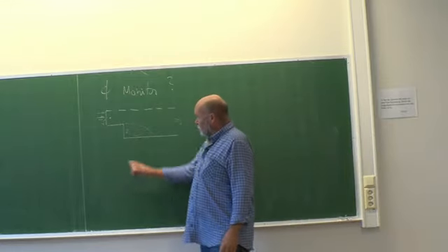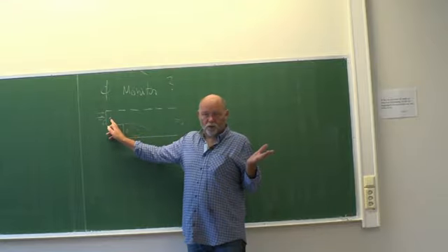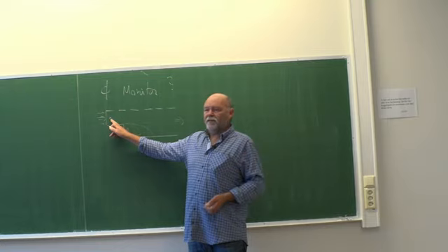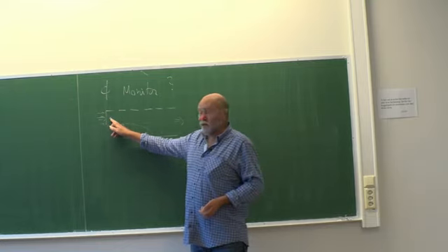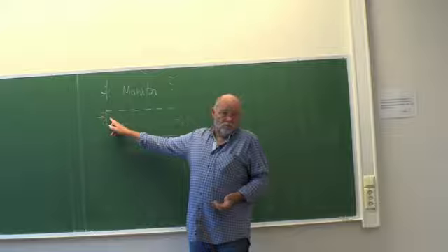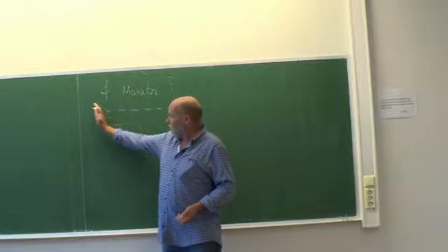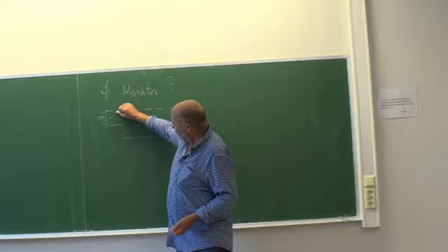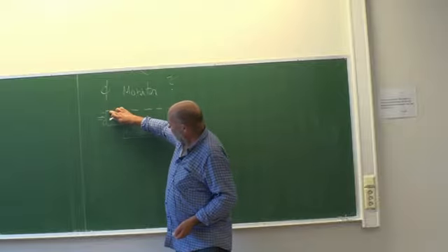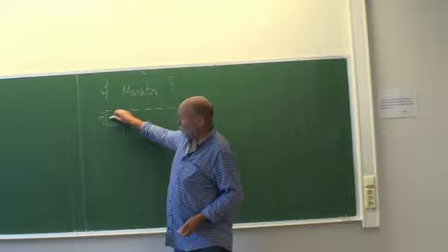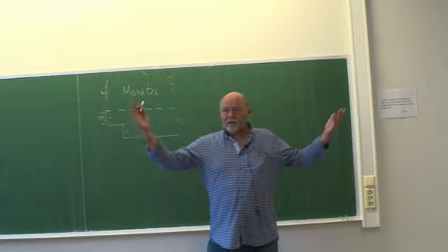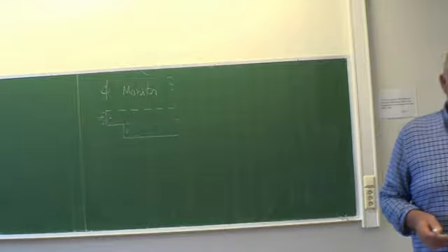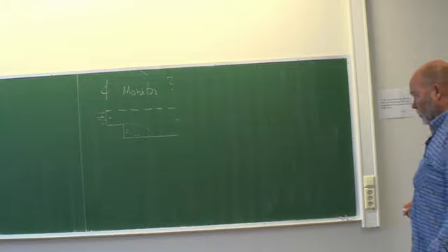If you choose that one, then you probably will find that the apparent order of your numerical scheme is 10 or 20 or something totally insane, because you'll get the same value here no matter what mesh you have. You send in a constant velocity. It takes some time for the boundary layer to grow here. Well, it doesn't grow up there actually. So the velocity here is going to be the same, independently of your meshes. It makes no sense at all. It's not a sensitive monitor. Totally stupid. Don't choose that one.